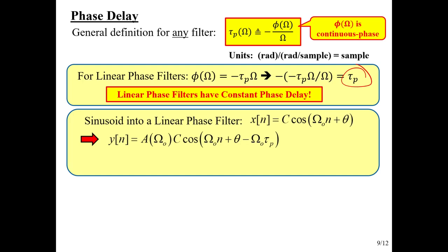So we know that the phase looks like this, and we know how to analyze how a sinusoid goes through a linear time invariant system. Two things happen. I covered this back in my review video for this course, although we did it for the magnitude phase, but it's obvious how it carries over. We evaluate the amplitude function at the frequency of the sinusoid, and we evaluate the phase function at the frequency of the sinusoid.